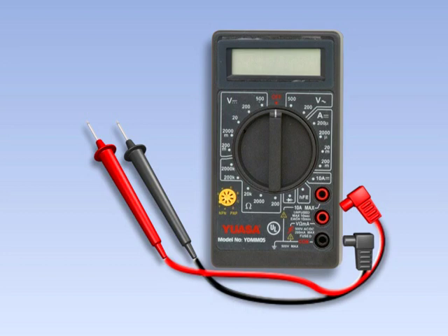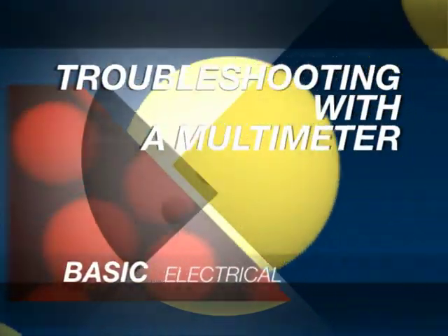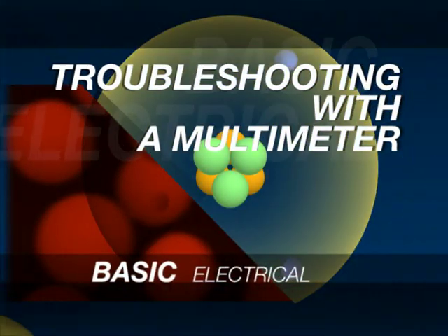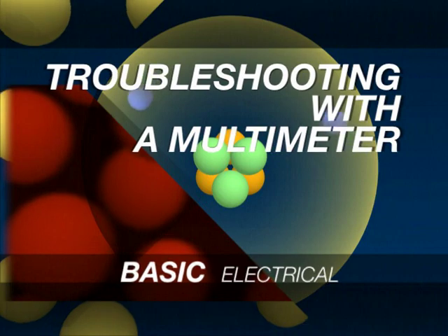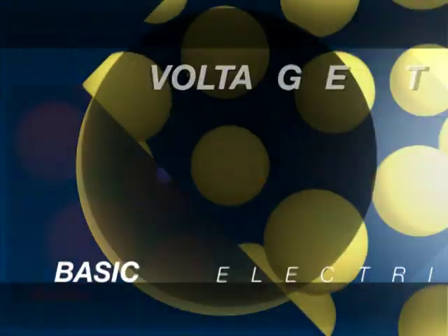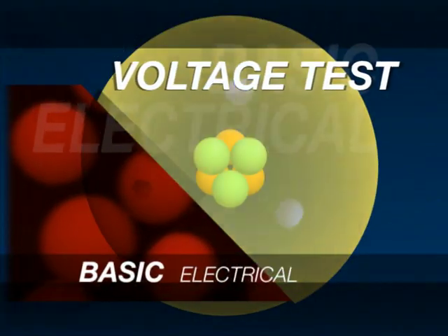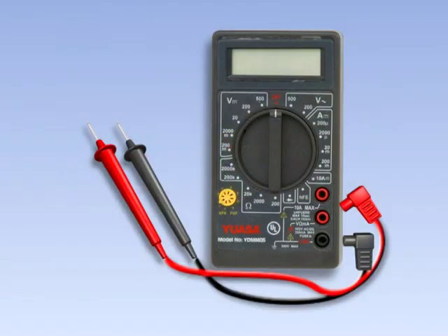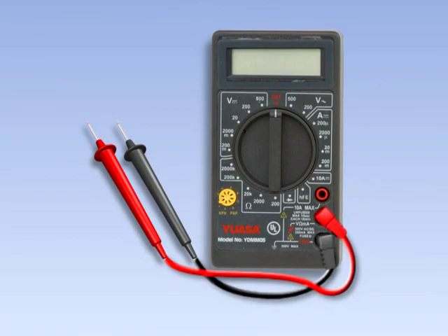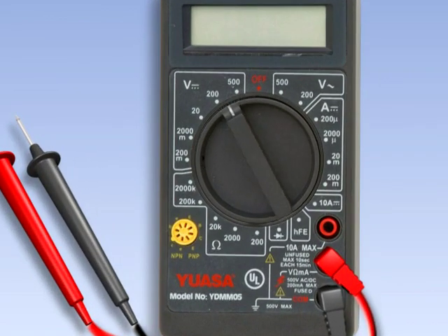The basic layout of a multimeter consists of a set of positive and negative test leads, a function selection switch, and a display screen. Most troubleshooting on a vehicle is done with the multimeter in either the DC voltage or resistance mode. To check for voltage to a load component, connect the test leads to their corresponding sockets, then turn the selection switch to the required DC volt range.